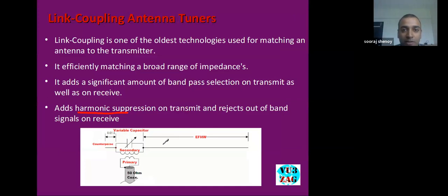In this type of antenna tuners or couplers, the counterpoise part is important. Whenever we talk about long wire antennas, the term counterpoise is important. It is a debatable point because most people don't agree about this counterpoise. But as per my experimentation, I found that the counterpoise is really important. And as per mathematical calculation, theoretically, it should be 0.05 lambda length with respect to the maximum frequency you are using for tuning. Okay.